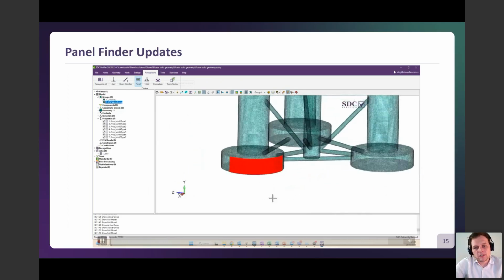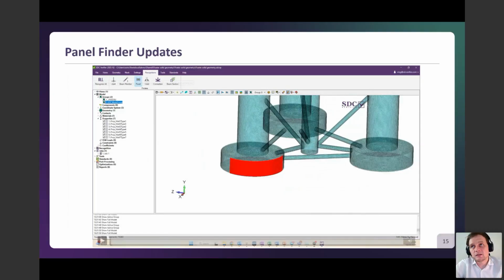So yeah, the bottleneck for us in adding this standard was the possibility to identify which plate is straight and which is curved, and then a possibility to define the radius. We were thinking about adding that manually, but then our development team managed to extract that from the FEA model. So we are able to read out the radius of the curvature. Therefore, we have all of the data necessary to calculate the plate buckling for curved plates also.